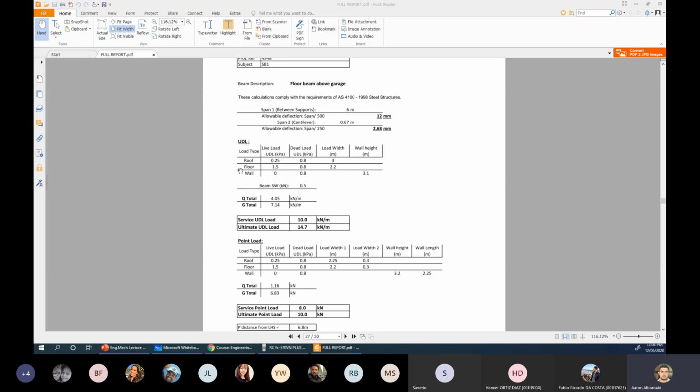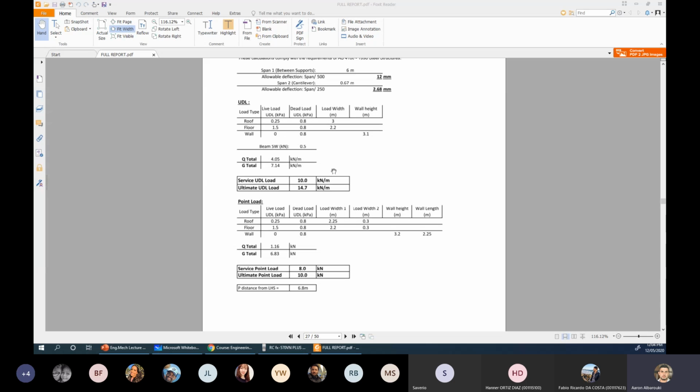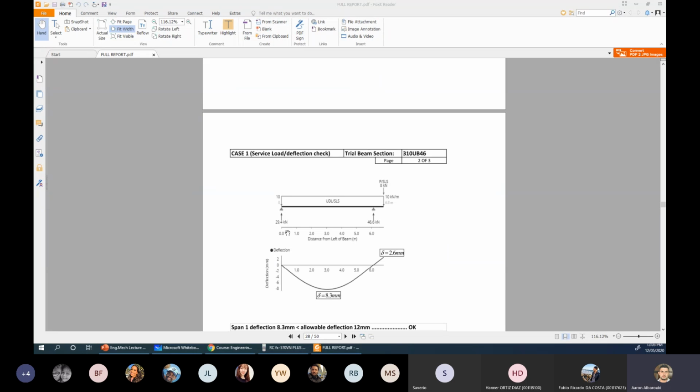How much is this beam supporting? How much live load and dead load? Live load refers to the weight of people, weight of furniture, anything moving. We call it live load, okay? Dead load refers to all the fixed loads or weight of material: the weight of the flooring itself, the weight of the beam, walls, roof. All of these materials are there and staying there for the design life of the project. And the wind load, regardless of whether we have wind or not, that's coming from the roof, the floor, and the walls above, for example. After I calculate all of this, we combine them and create some safety factors into them. We will study all of this later on. But the point is we get to these loads here, and that's where you guys are at now.